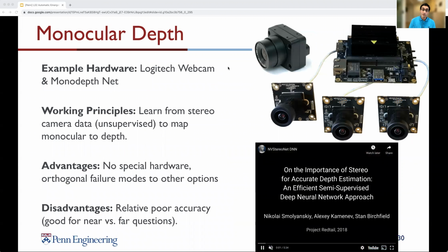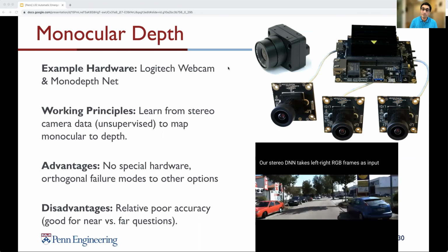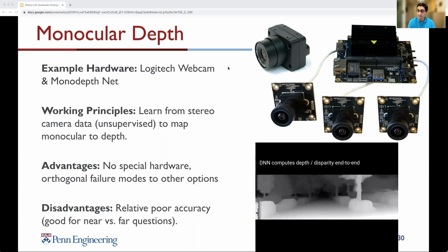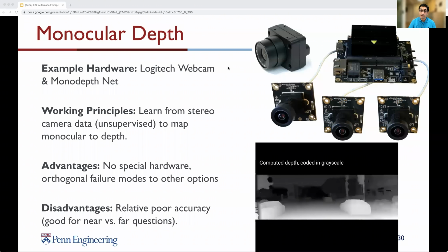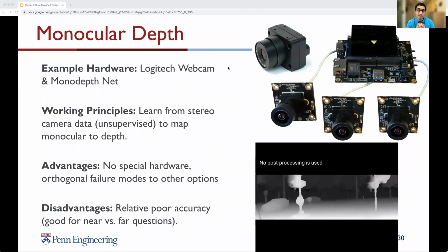So then we look at monocular cameras. That's the very basic building block of computer vision. And so with classic computer vision, you can capture the vanishing point down a corridor, you can detect lane markers, and so on. The nice part is that we can also detect depth with monocular cameras nowadays using machine learning approaches such as monodepth, right? So with supervised learning on the LiDAR and the monocular camera data, we can capture relatively good depth estimates, making this a cheap and powerful depth sensor.